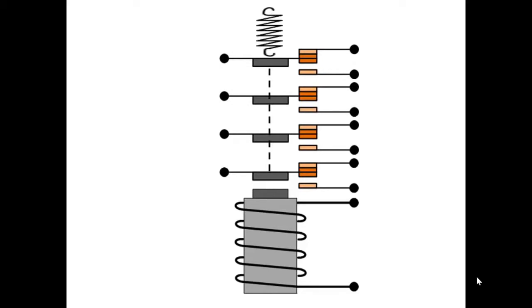They're all operated mechanically in synchronous, and we have a heavier switch, and we're going to need actually a heavier relay coil with more windings and more current, because remember that we have a heavier spring to pull back 4 Form C sets of contacts instead of 1. And we have to lift against gravity the 4 armatures. Actually, there's probably going to be 1 armature but 4 sets of contacts.